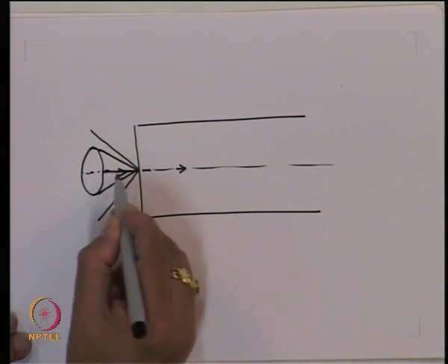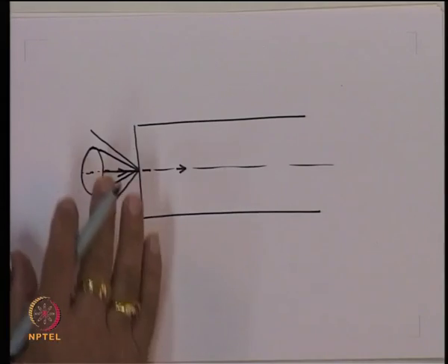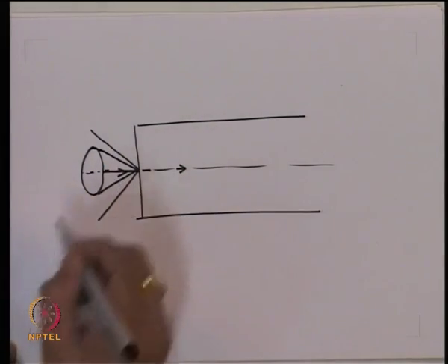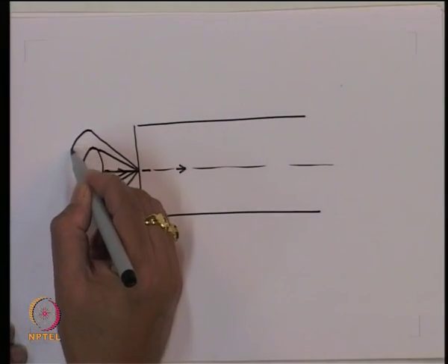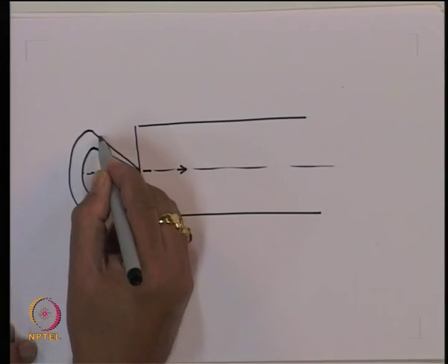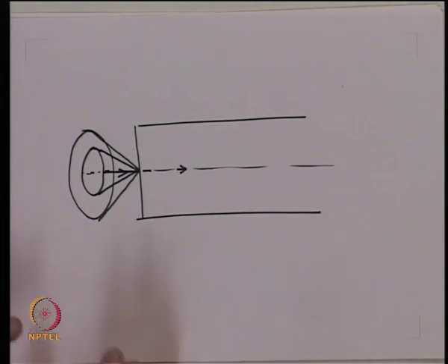So, one ray is the one which is going straight like this. Second is the ensemble of rays which are making this angle. Third could be this one, and that is all. So, what we find now is that there are discrete ensemble of rays which can be launched inside the optical fiber. And when we take the collection of this ensemble of the rays, that gives you interference pattern inside the core, and as a result you have a very definite intensity patterns formed inside the core of the optical fiber.